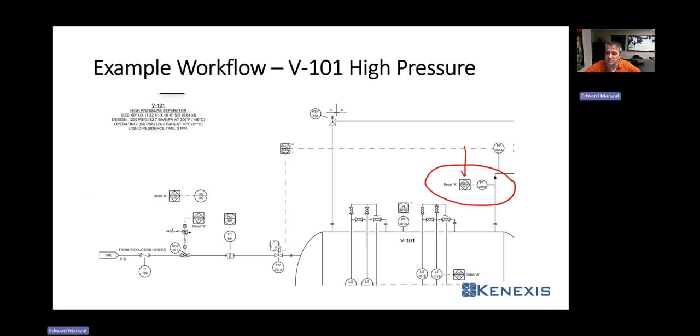to USC 101, and those of you in the know, that should actually be UZC, a relatively recent update to the ISA 5.1 standard created this new Z designation, which I really don't care for. I mean, S is safety, so USC would be multivariable safety controller, but alas, no. Instead, we're going to do a multivariable SIS controller.